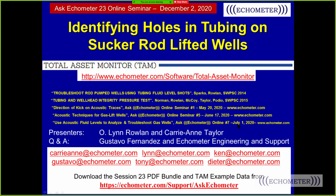And then in July, we did one on shooting fluids on gas wells. When someone first told me that we've had holes in gas wells, I said there's just no way there's holes in tubing because there's no sucker rods, and that was completely wrong. There's corrosion, and there's condensation that occurs inside tubing on a gas well when the vapor condenses and runs down the tubing wall. If there's any acid gas in the tubing, then it can absorb into the liquid and start to etch away the tubing wall. So it's not uncommon to have a hole in gas wells, and that's discussed in this presentation here.